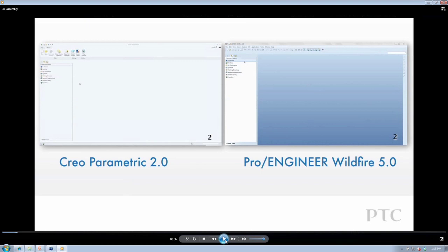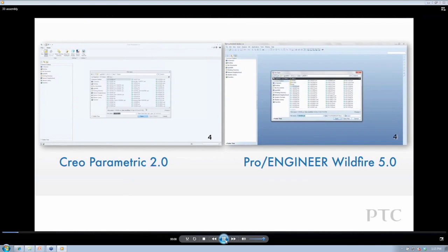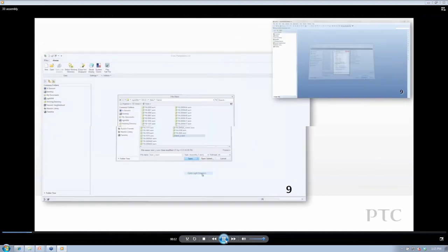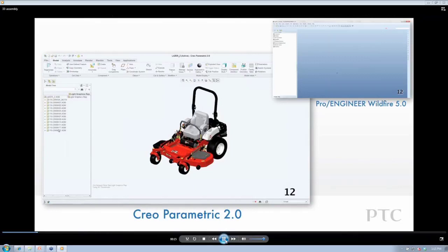One of the biggest enhancements you'll see in Creo Parametric 2.0, and assembly specifically, that customers are the most excited about, is the ability to do what's called a lightweight graphics option. So I can open up a very lightweight graphics option, or graphics rep, and this is using some Creo View technology that, if I want to open up a master rep of an assembly, it would take maybe a few minutes to open up a large assembly, but the graphics rep is only going to be a few seconds. And if I want to change that representation, maybe exclude a few things, but I see all of it. I see the whole thing. That's just a huge benefit.